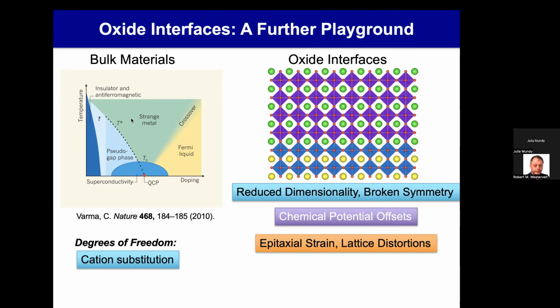So if I take a material that wants to have an atomic spacing of 3.9 angstroms, and I put down on it a material that in its ground state wants to have 4 angstroms, in the ultra-thin limit, it'll form this cube-on-cube structure. It has more energy to relax at the interface, what have you. And you can actually stretch or squeeze materials by 5 or 8 or something like that percent.